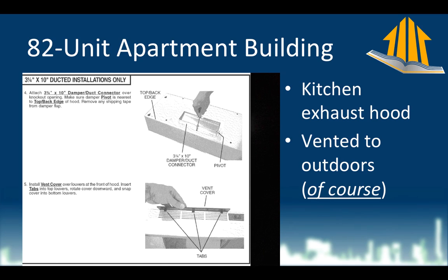The general contractor takes out the box, opens it up, and of course out comes the vent cover, which is good, and also a backdraft damper, which is essentially a flap that's designed to keep air from coming back down this hood from outside and coming out into my kitchen area. That's terrible news, because what that means is that there is no backdraft damper installed yet. So what we had to do in this case is, this building is almost finished. We had to uninstall all of the kitchen exhaust hoods to install this backdraft damper, because there is no way that that is not going to get installed. That would be disastrous for the performance of this place.